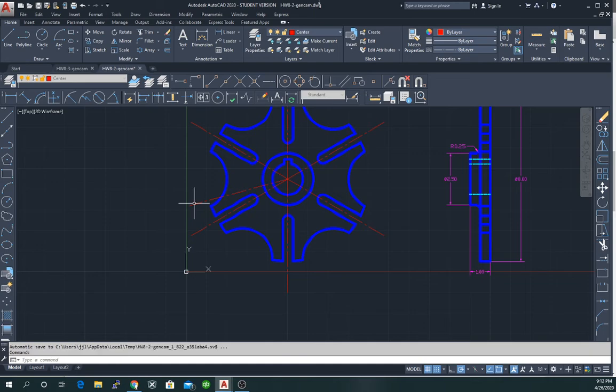And then I'm going to add another line at an angle of, excuse me, I said 15 degrees, but what I really meant was minus 15 degrees off of the negative x-axis. And then I'm going to go plus 15 degrees off the negative x-axis. And again, I'm going to do a length of 5.